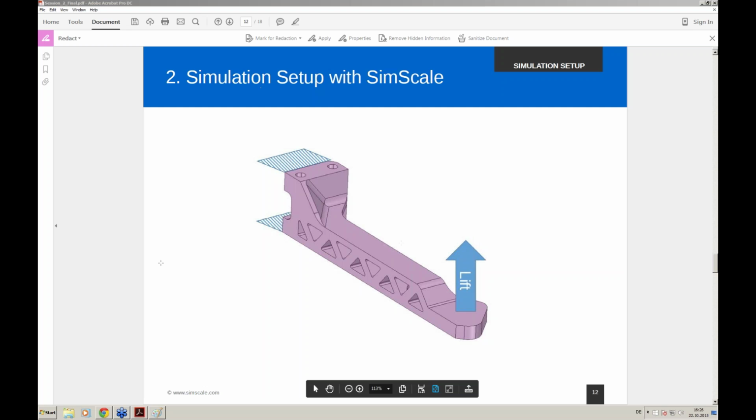When we simplify the problem, what we can say is that we have this lift force on the arm, which is created by the propeller and by the engine. This is what we investigated last time. For a first shot, we will just investigate if this lift can create structural problems on this drone arm. We will take only the drone arm and say it's fixed here and here.